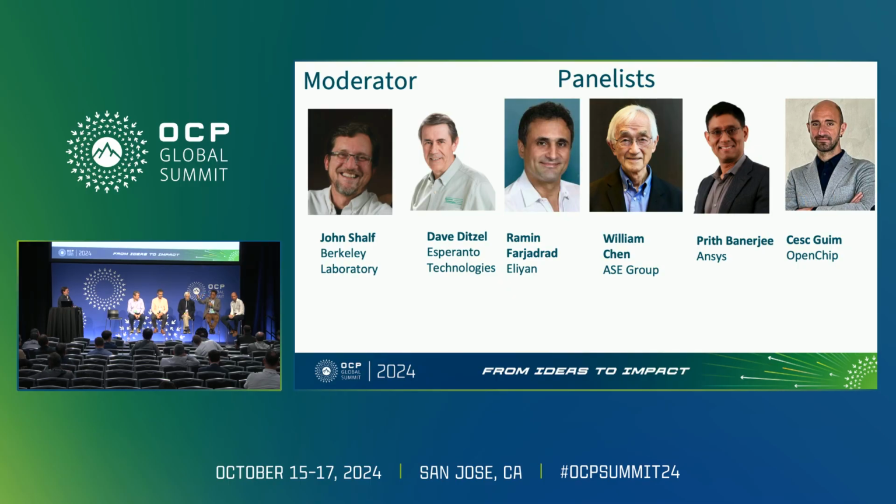In each of these verticals, people are thinking about the use of chiplets, but the real use case will be not chiplets using the same 2 nanometer technology, but a chiplet having an IP block with 7 nanometer, another with 20 nanometer. You pick the best of those things because that is how you'll get the lowest cost and the highest performance designs.